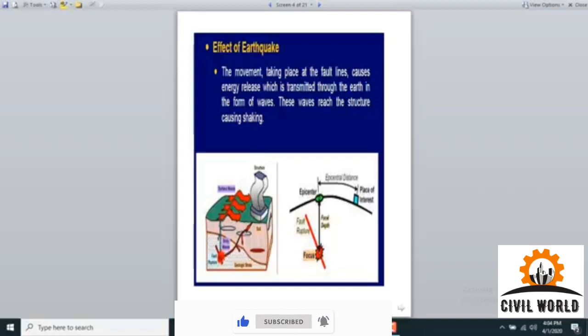This is a structure, so these waves will hit that structure base, which will then transfer some shear force up to the top of that structure. This force is normally called base shear, and the conversion of base shear at various heights of the structure are called story shears. So two types of shear forces are developed in every structure which lies in the way of the waves. One is called the base shear and the other are called the story shears. These two forces are also dependent again on these two things, the focal depth FD and the epicentral distance ED.